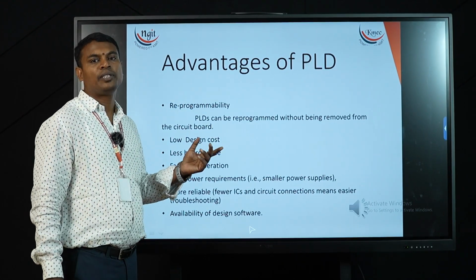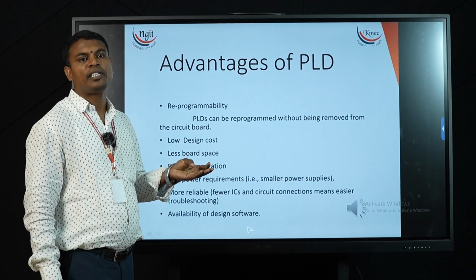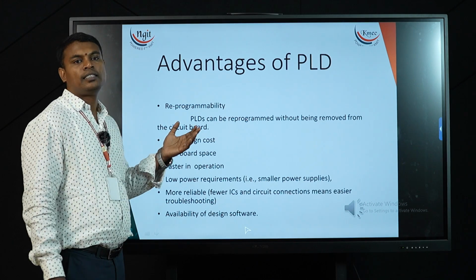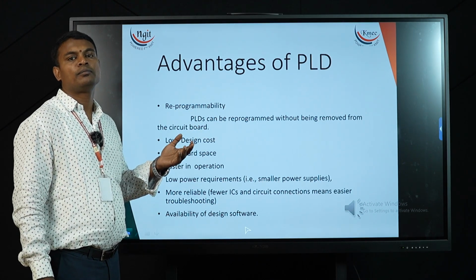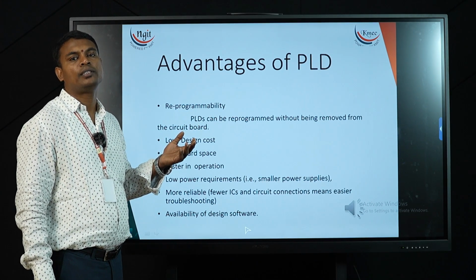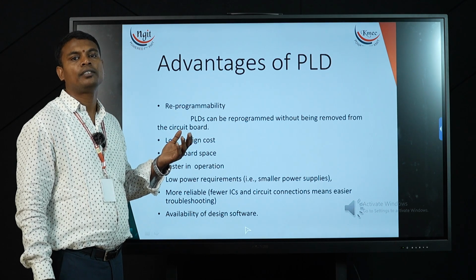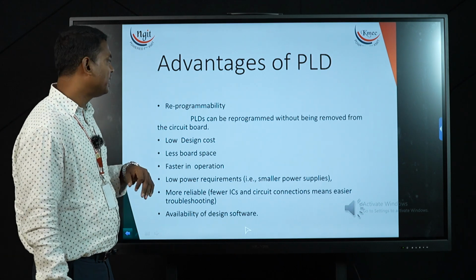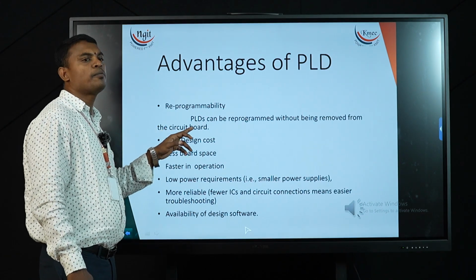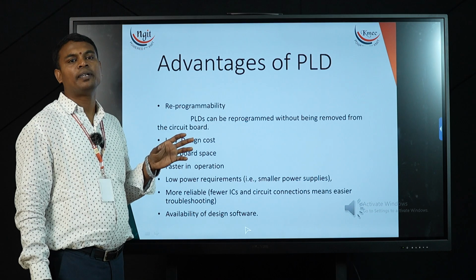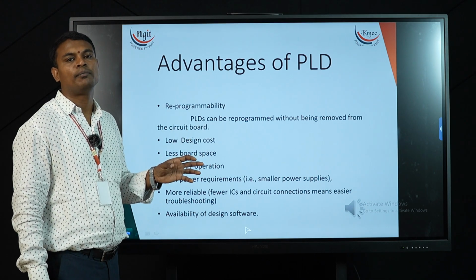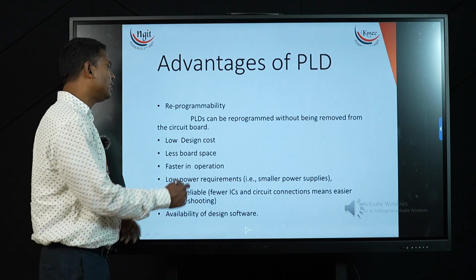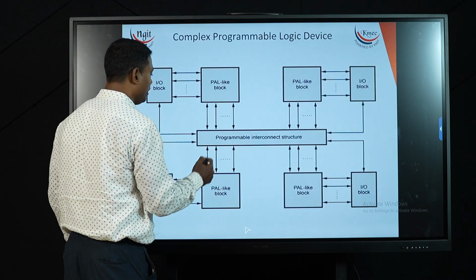The PLDs which we discussed are programmable read-only memory, programmable logic array and programmable array logic. Those were the designs, and we constructed some using full adders. We constructed PLA, PROM and PAL. So some of the advantages of using programmable logic devices, like reprogrammability. Once we programmed one device and we utilized its function completely, we can use the same device for any other functionality. So that's the reason we call it reprogrammability.